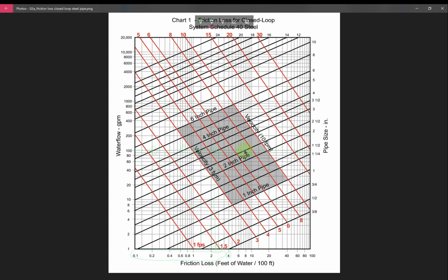Now, if we select the next value, which is a 2.5-inch pipe, you see we are going beyond the value of 4. So in this case, the pipe cannot be selected according to ASHRAE standards. So the optimum value of pipe diameter in this case is a 3-inch pipe. And as you know, 3-inch is approximately equal to 75 mm. So now let's go back to Revit.